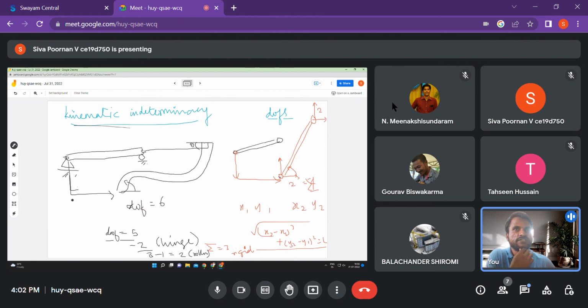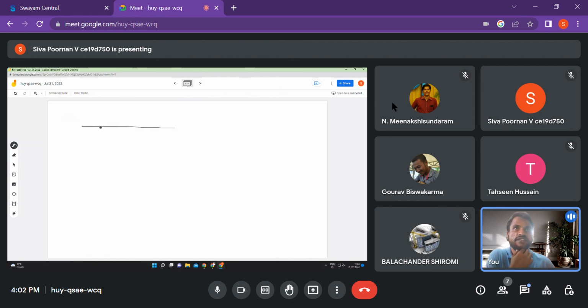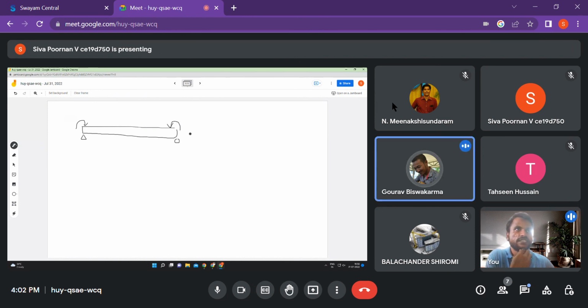So what are the two things that we have to find out in a beam that is simply supported? By the way, remember that we have already taken the axial constraint into effect. Okay, if axial constraint is not there, it is 3. So what are the three kinematic indeterminate quantities here? In a simply supported beam, we can have a rotation here, we can have another rotation here, and an expansion. If the expansion is not there, then the kinematic indeterminacy is going to be 2. Okay, so we just need to find out the rotation at these 2 points to know the complete profile.